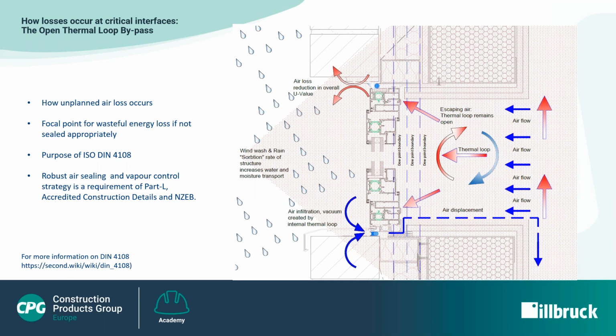This may be even more pronounced where two or more gaps exist, one above the other, as a chimney effect can be created with the cold air infiltrating through the lower gap and the warm air escaping through the upper gap. If the temperature is set high, or if the heating system is efficient, then the pressure gradient is more exaggerated. The convection cycle is faster, and hence the convection heat loss is actually greater than at lower temperature settings or with a less efficient heating system.